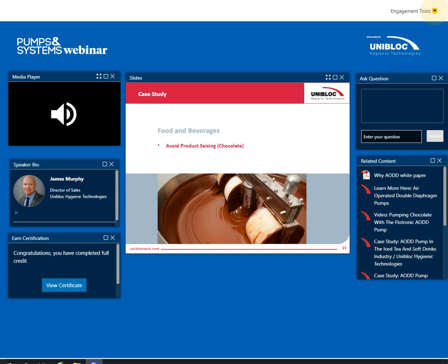Yeah, okay. So the CFM, that's essentially the air consumption, is directly related to the size of the pump and how fast you intend on operating the pump. So if you think of a 1/2-inch pump versus a 4-inch pump, the 4-inch pump is going to have a greater CFM requirement to hit various levels of the performance curves. So larger the pump, the more CFM. And put it in more common terms, the larger the engine in your car, probably the worse gas mileage you get.